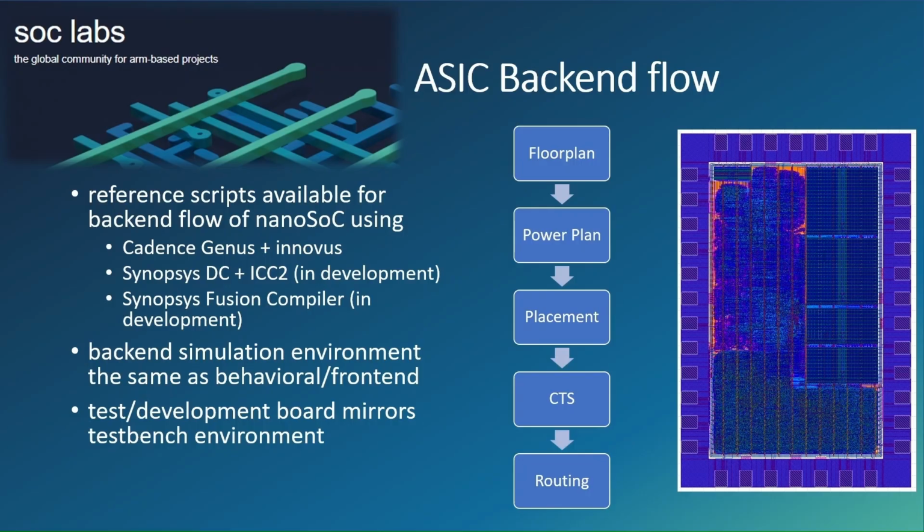In terms of the back-end simulations, so gate-level sims, post-route sims, the test bench that we developed for the front end is almost exactly the same as the back end. So you don't have to preload any of the RAMs. You can load it all over the external interfaces, which then gives you more confidence that the silicon you get back, you'll actually be able to talk to it.